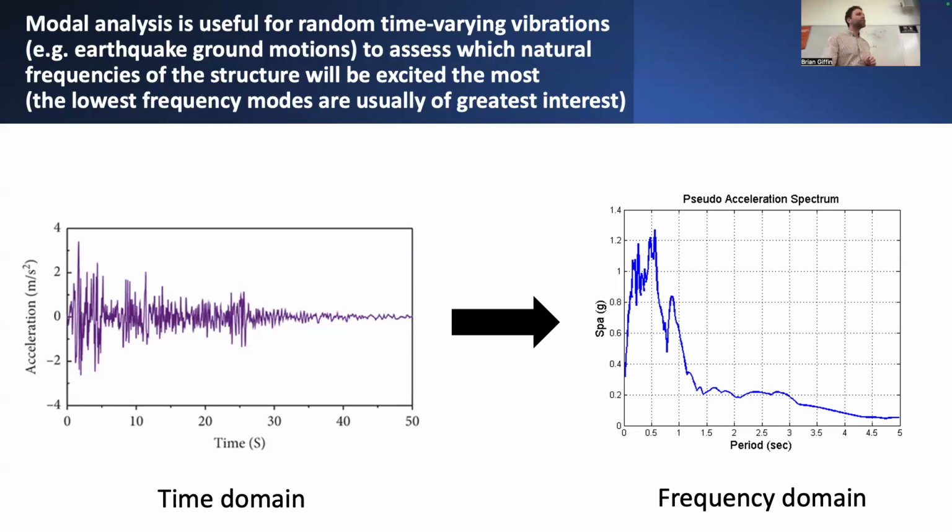So typically, earthquake excitations tend to excite most these lowest modes of vibration in the structure, which usually means that if you're trying to analyze a structure like a multi-story building subjected to an earthquake, it's usually sufficient to just look at the first couple of modes of vibration, the lowest frequency modes, and then figure out the effective excitation in each one of these modes, the effective spectral accelerations in each of those independent modes, given some time history of deformation or accelerations from some external loading.